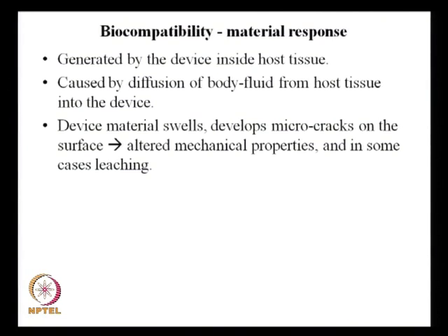Now, if the body fluid diffuses into this device, and then the device material swells, that is the third point I write here. Device material swells, develops micro cracks on the surface, altered mechanical properties, and in some cases leaching. So, these are the problems that would happen if the body fluid enters into the device. Because of that the device material swells, it develops micro cracks.